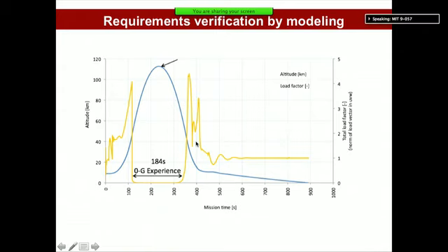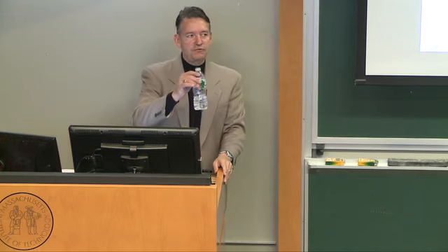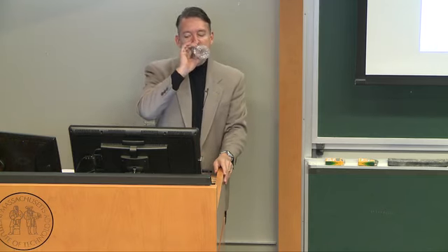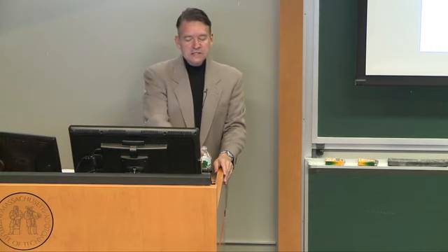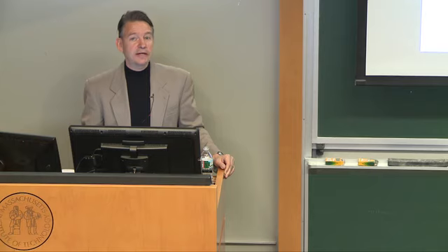And the whole reason we're doing it is for this period here, that 0 G experience. So when the load factor goes to 0 or near 0, that's when you get weightlessness. And it turns out for this particular flight profile, we would experience 184 seconds, about 3 minutes of weightlessness. This is pretty similar to the flight profile that Virgin Galactic is pursuing, by the way.